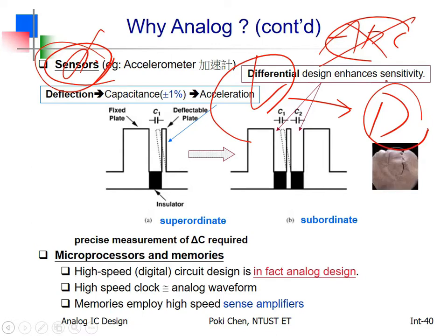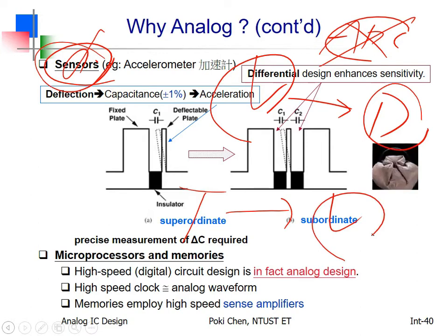For example, temperature sensor. What does it mean? To convert temperature into what? As you like. You can convert temperature into voltage. That is some kind of sensor. But it's not good enough. Our chip doesn't read voltage signal. In the baseband, they can only process digital information, right? So you need the help of ADC to convert the voltage into digital.